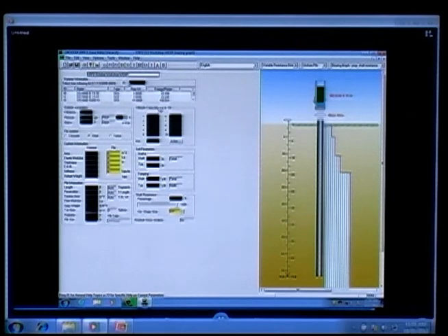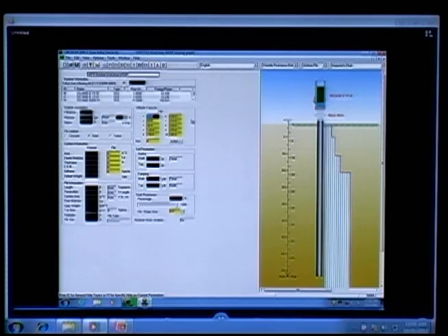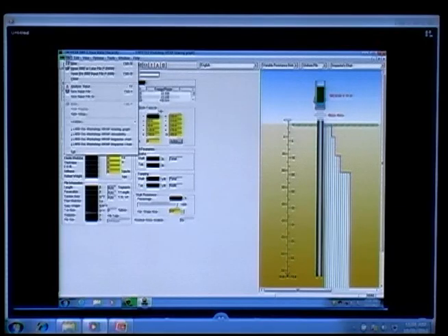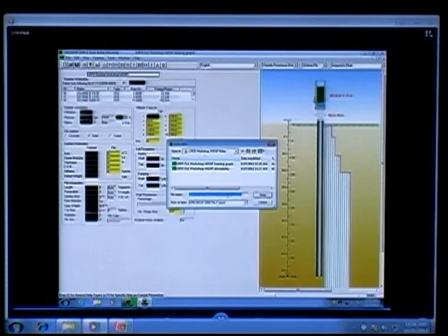The next analysis is to generate an inspector's chart. Go to the upper right-hand corner, pull down the Bearing Graph Prop Shaft Resistance tab, and select Inspector's Chart. Specify the target nominal pile capacity, for example, 200 kips. Save your inspector's chart output file. Select File and click on Save Input File As. Go to the directory and type in your new file name.